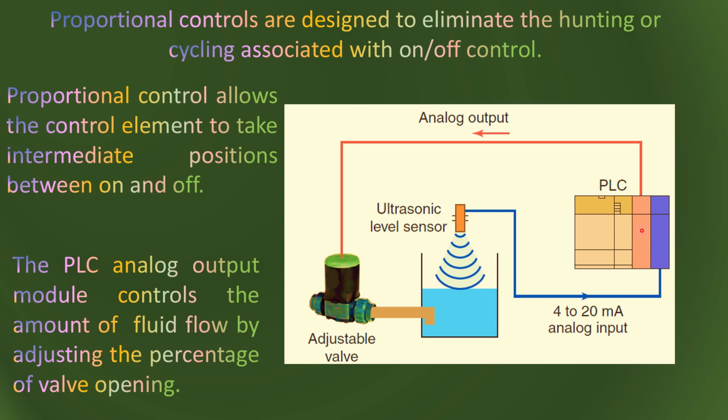Then inside the PLC there will be a controller. That controller can be of many different types. Those controllers can synthesize a control signal, and that control signal we can send to the actuator. Again we can convert the signal to 4 to 20 milliampere current or some optical signal, and then when we come close to the device itself, it is again converted to the voltage signal to move the motors inside the actuator. So this signal depends upon the actuator, which type of signal is required to actuate it.